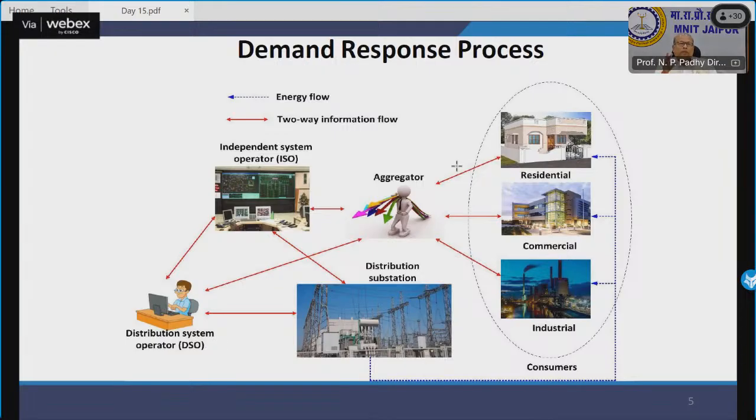So you may participate in a demand response program where you can say, I may compromise my heating system by a few degrees Celsius, subject to the price being a bit less. Instead of living in a pleasant environment of, let's say, 22, I'm ready to live with 20. And similarly for air conditioning loads, instead of 16, I'm ready to live with 18.